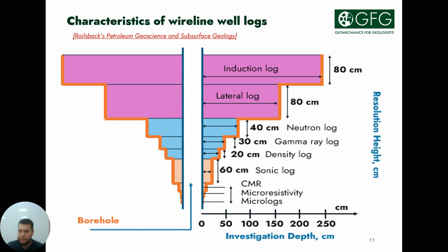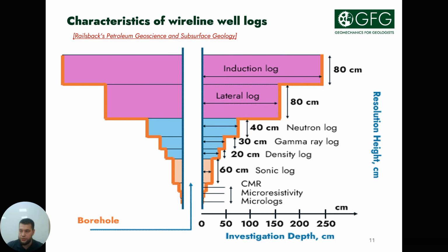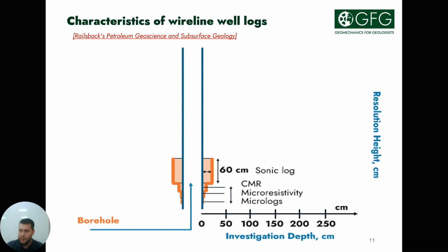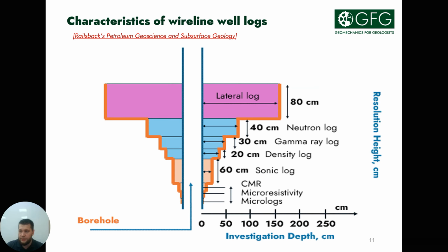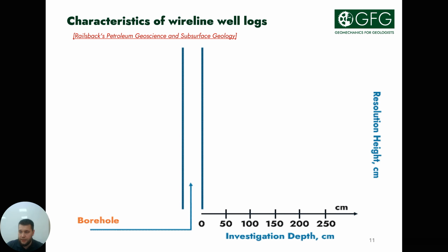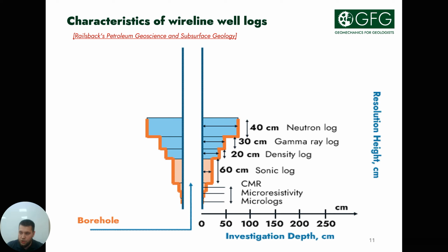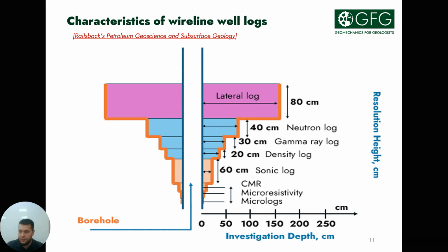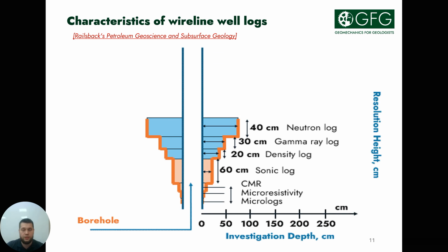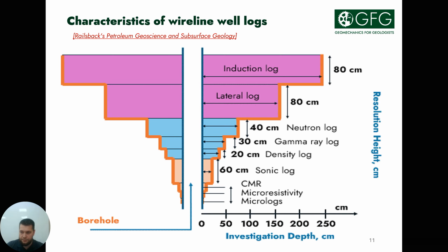Neutron and radioactive methods have a lower resolution. Density and acoustic logging methods, which play the most important role for geomechanics, have a reasonable vertical resolution and depth. For this reason, it is necessary to do a careful validation of the initial density and acoustic logs for modeling. These methods will not work in intervals with an increased borehole diameter, such as caverns and casings.